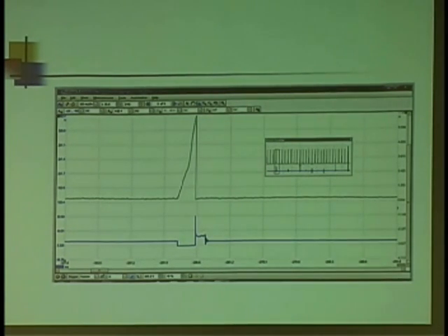So that's why they give me this little thing called an attenuator. It takes that incoming voltage and steps it down. In my case, it's by a factor of 10. So if I take in 500 volts, it's only 50 to my scope. And then I can change the scaling on my scope to read the number. Every scope has that. So check with the manufacturer of yours to see what you have to do to attenuate the signal so that you don't blow your scope up.